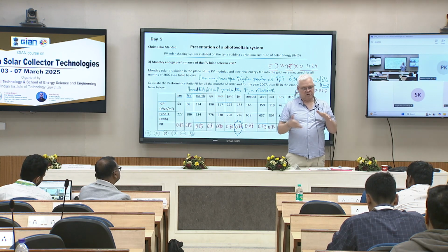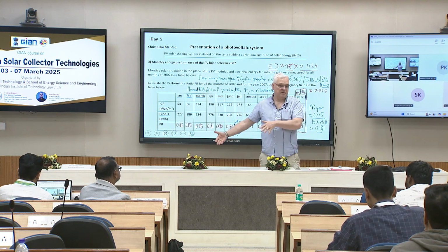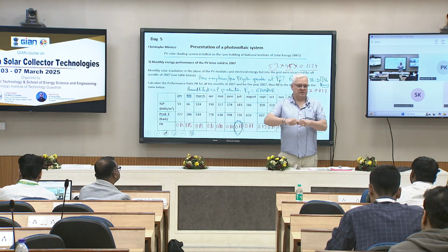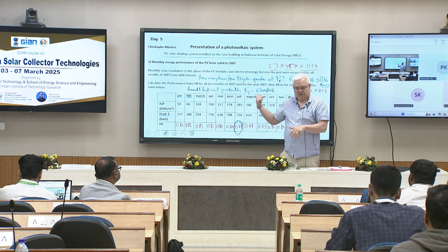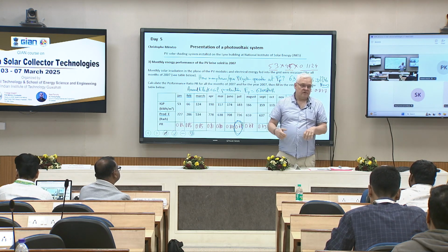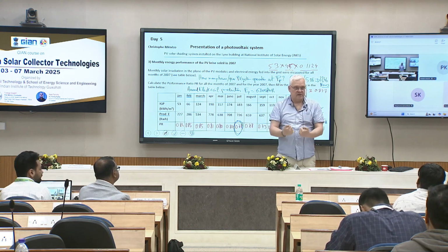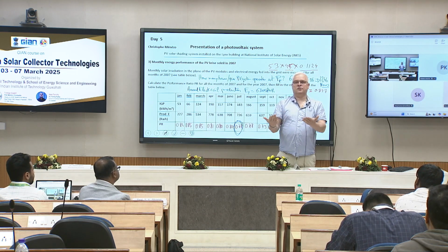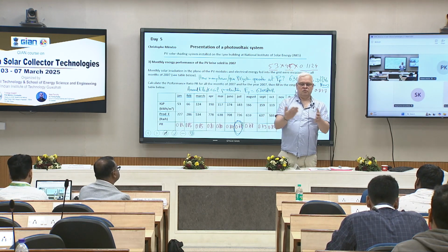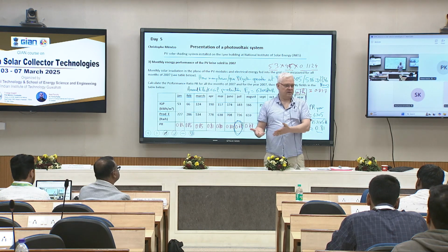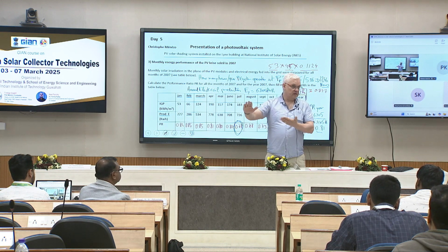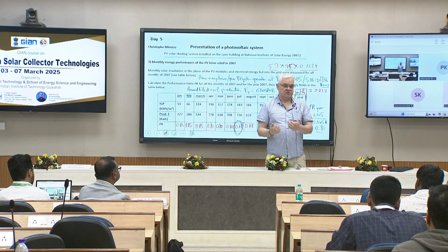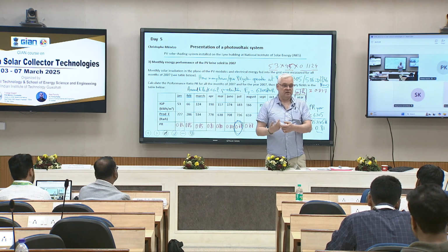But what you can change is if there is a problem in your PV plant: cables inducing more than 1% of loss, or soiling that you will decrease. You are expecting that for such a sun you should have this, but you don't have it. Maybe there is soiling that reduces incident radiation and things like that.